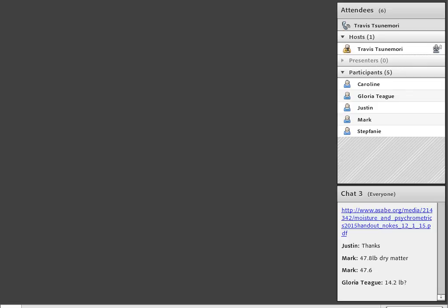And then the last one that we're asking for is the dew point temperature, and that one is straight to the left. So go back to our point, and we follow the horizontal line to the left, and where it intersects the curved axis is the dew point temperature. That's 100% saturation, and I read off 54 degrees Fahrenheit.